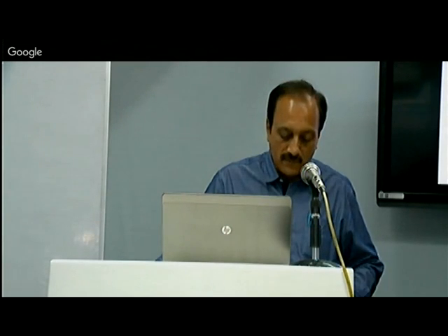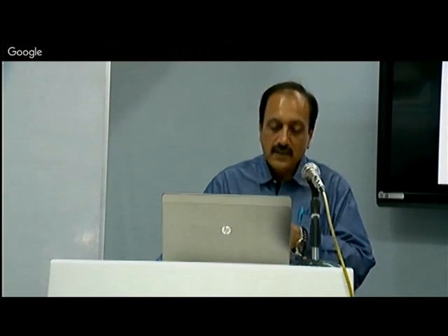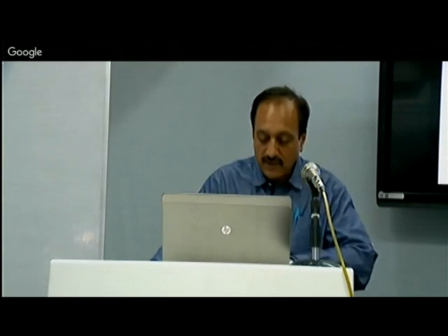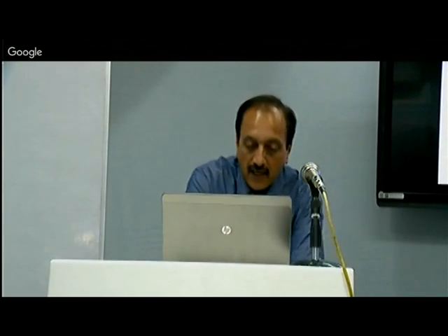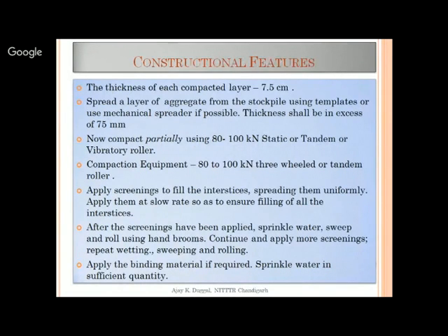अब जब हम कहते हैं वाटर बाउंड मैकेडम, तो इसकी मैं आपको पिक्चर थोड़ी देर में दिखाता हूं. अब ये पार्टली मैनुअल है और पार्टली मैकेनिकल है. मैनुअल इन द सेंस जो स्क्रीनिंग एप्लीकेशन है that is manually done. The key issue here is the success of water-bound macadam depends on good application of screenings, proper distribution and then the compaction. क्योंकि ये screenings आप ऊपर से apply कर रहे हैं, so in some cases what we do is that